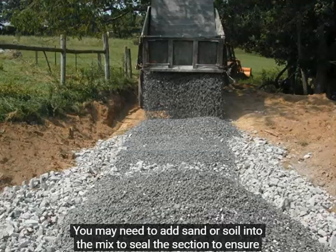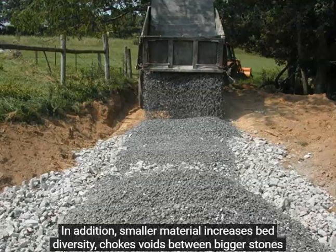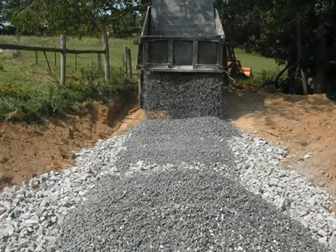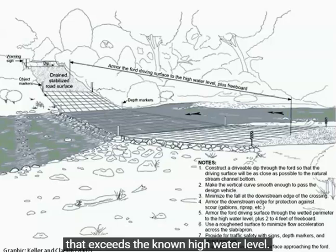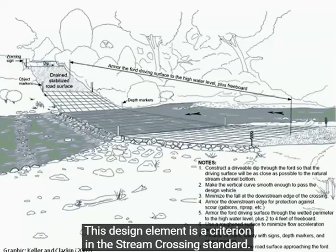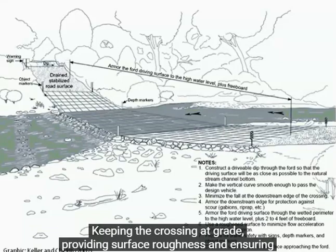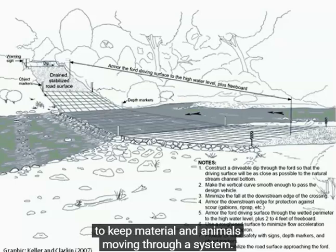You may need to add sand or soil into the mix to seal the section to ensure that the stream doesn't percolate into the crossing substrate. In addition, smaller material increases bed diversity, chokes voids between bigger stones, and helps preserve passage quality. It's also important to extend the driving surface of the crossing to an elevation that exceeds the known high water level. This design element is a criterion in the stream crossing standard. Keeping the crossing at grade, providing surface roughness, and ensuring that the downstream edge doesn't produce a sharp drop in water surface is the best way to keep material and animals moving through a system.